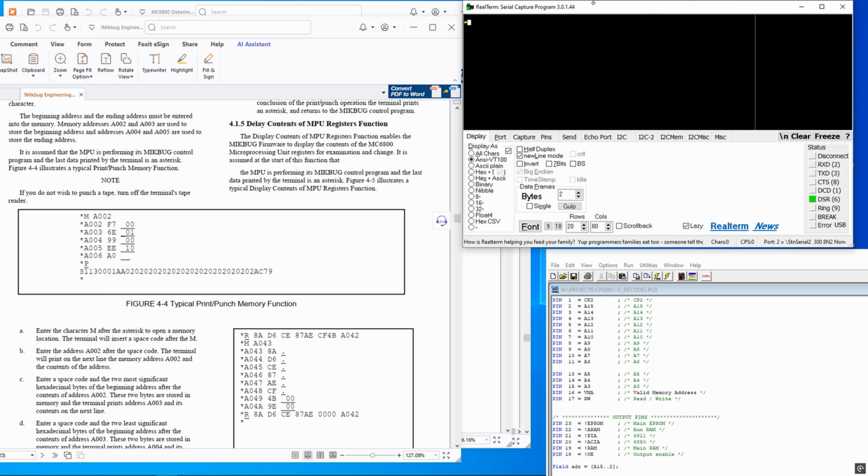However, when you actually try and give it a command, so memory view, so it's M, and it produces the space, then the address, and enter. It doesn't do anything. R should display the processor registers. It starts and then gives up, so there's something still not quite right.